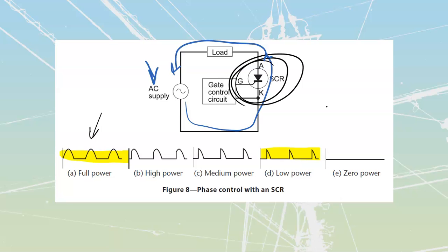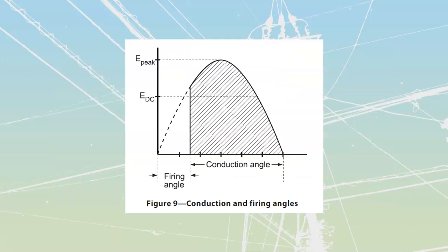And phase control is going to be defined into two distinct periods of time. We are going to have our conduction, and we are going to have our commutation. First of all, because it is a one-way device, each SCR is only going to see half of a cycle. And half of a cycle is called an alternation. Alternation. You could draw a little cowboy hat. Anyways, this is an alternation that we have here, and that alternation is broken down into two sections.